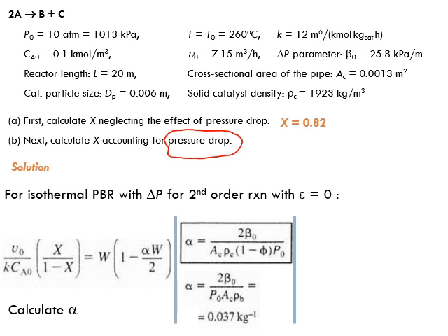So that means if you have higher values of alpha, you'll have more pressure drop per kg of packing. Okay, so beds with higher alpha experience, or the flow experiences, higher pressure drop. What about if you don't have pressure drop? Then what happens to the value of alpha? Yes, correct, the value of alpha would be 0. No pressure drop, that means alpha is 0.